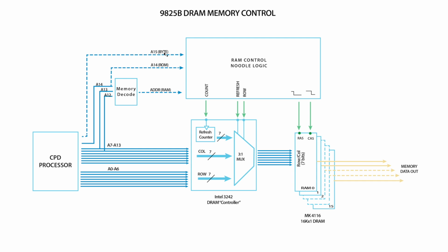A15 is actually not used for addressing, it's used to indicate byte operations. We'll ignore it. And finally, STM is the start memory cycle. It's the most important timing signal, and we repaired it when we were doing the ROM repair. So that's it. Basically what our noodle logic has to do is generate those 5 outputs out of those 4 inputs plus the clock, and it's way more complicated than you'd think.